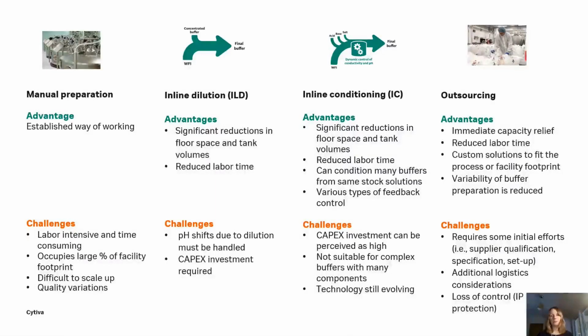Inline conditioning has similar advantages as inline dilution, but here you can reduce the floor space and tank volumes even further, since you can reuse the same number of stock solutions for several buffers, and this will also bring significant savings in labor. Then, since you have these more sophisticated algorithms to prepare your buffers, you will have a higher quality control of your buffers as well. The challenge here, on the other hand, is that the capex investment can be perceived as high, and it's not suitable for complex buffers with many components, and the technology is still evolving.